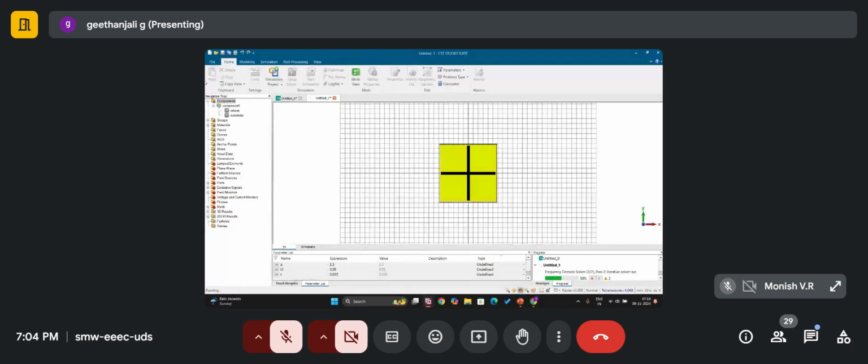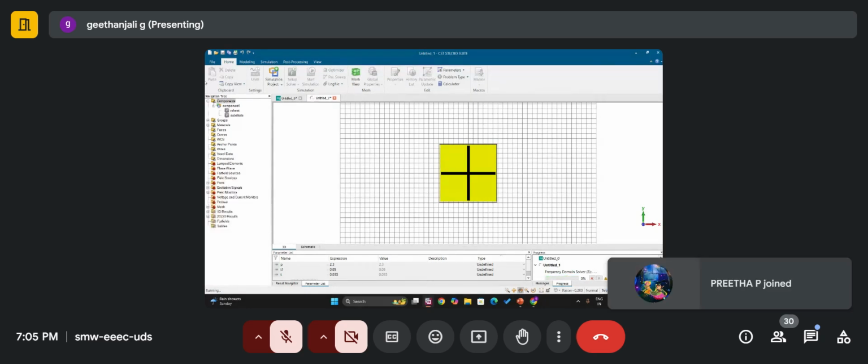You can also integrate this band stop and band pass FSS to achieve both the absorption and transmission characteristics. To achieve those characteristics, you have to incorporate the PIN diode, as I said before. In a PIN diode there will be on-off conditions, where in the on state it will behave as a transmitter, and in the off state it will behave as an absorber.